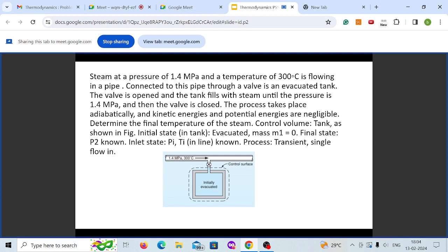In this control volume, again, basically you do an energy balance. You see what the interactions are. You have some mass coming in and some mass going out. The mass coming in will bring in some energy in terms of enthalpy, and the mass going out will take away some energy. Then you have the kinetic energy or potential energy with which the mass is coming into the system, and similarly going out.